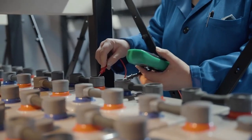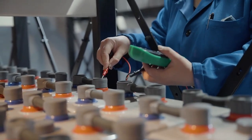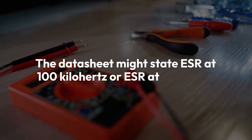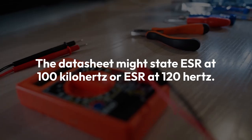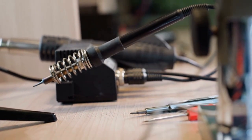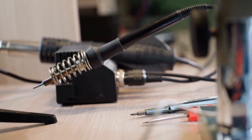Pay close attention to any specified test conditions. The datasheet might state ESR at 100 kHz or ESR at 120 Hz. Temperature also affects ESR, so check if a specific temperature is mentioned, usually 25 degrees Celsius.